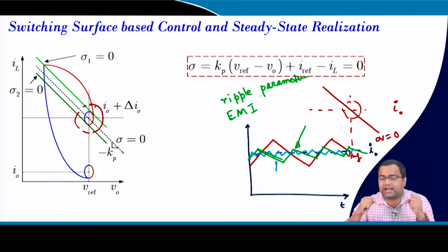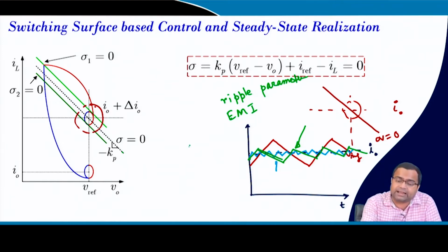So, the objective is that we have some ripple constraint, that means we cannot reduce too low, then the switching frequency will be very high, and that switching frequency can lead to a lot of switching loss and the efficiency can drop. We cannot have very large current ripple. So, who will decide? That means some delta IL which will be desired, that I need to set, the desired current ripple.